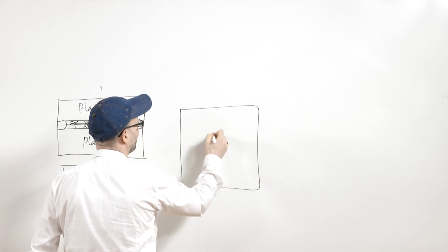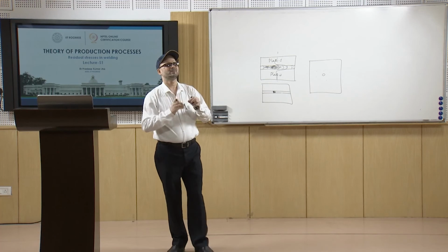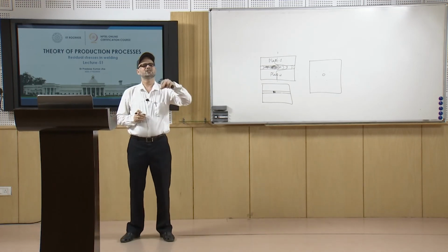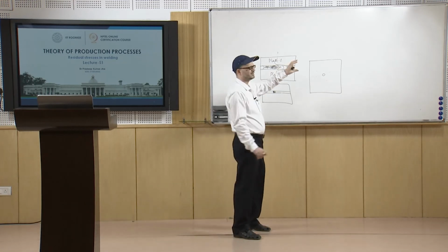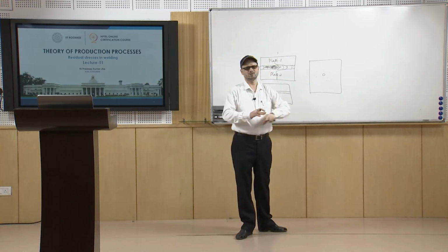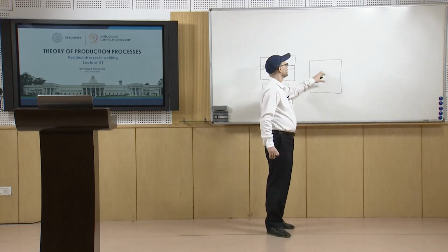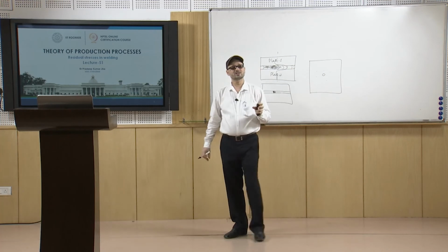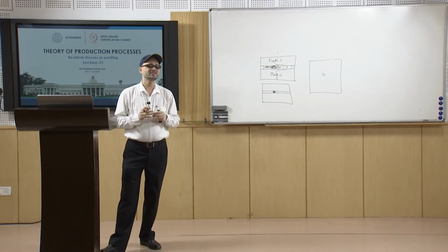Suppose at this point you are doing the drilling. The strain gauges or rosettes which are there at different points may have some displacement, or there will be some strain because the stress is being released. So, that may lead to values of strain at these points. Now, these strains at those different points may be measured using the strain gauges, depending upon whether you are dealing with a biaxial, uniaxial or triaxial state. Then, using the properties of elasticity, you can calculate the stress value at this point. So, that is the main concept of measuring the residual stresses.